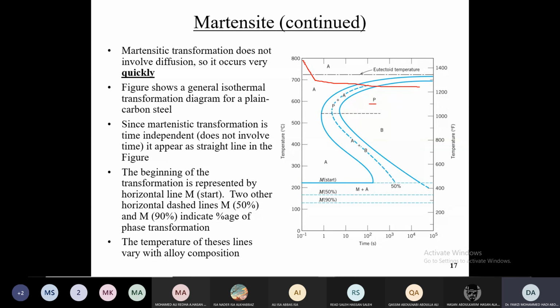If your heat treatment is moderate, you avoid the nose of the TTT diagram and you fall into there, and then you are going to form the bainite phase. Of course, this is a small jump in temperature. You could have a bigger jump in temperature to produce another microstructure. As your delta T is bigger, you will be producing the fine pearlite here, right? And at the upper temperature, with the smaller delta T, you will be forming the coarse.